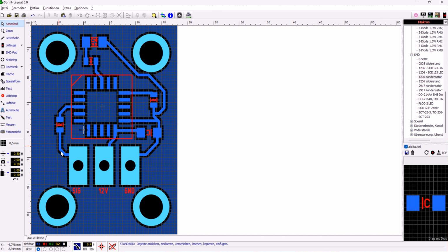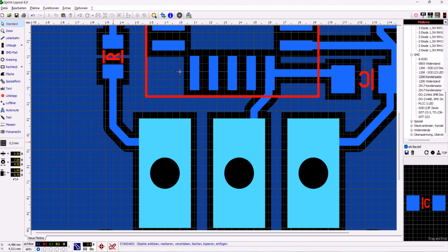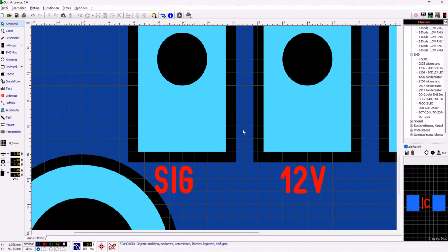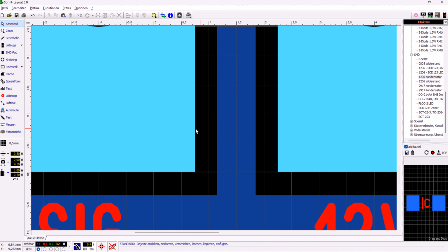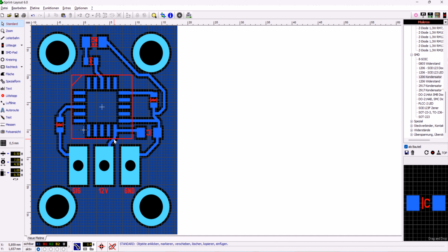And by standard, there's a clearance from all your copper parts like pads, traces, etc., or vias like that one. That is a mounting hole on this PCB. There's a clearance between those things and your copper. So the black area, there is no copper. That will be etched away. So right now the copper layer doesn't do much, except for, as I said, the PCB manufacturer is maybe a little bit happy that they don't have to etch away that much copper, but you don't gain much. There's also not real good shielding, because the plane right now is not connected to anything, so there's not a defined level where this plane is.